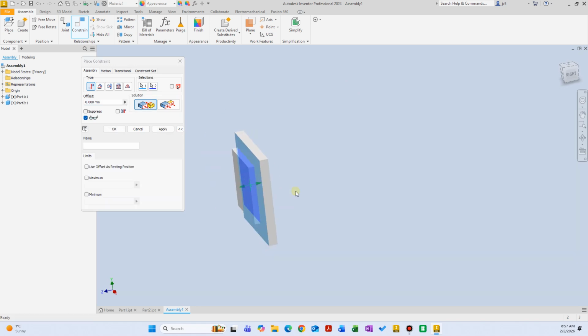And this is kind of like your two hands when you're clapping. That's how they come together, right? The inside of your left hand and the palm of your right hand, they mate. And that's the mate constraint. And that's basically you're doing the same thing between two components. And you can see it in the preview. The arrow coming from this face here, highlighted with red, and the arrow coming from that face of the yellow transparent box, and that's where they are mated.